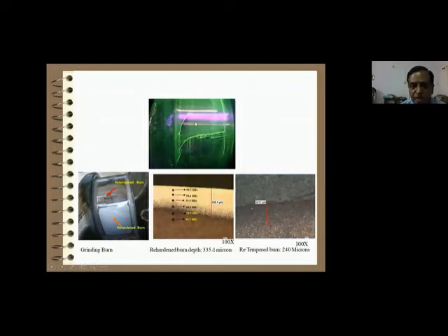Now this is a typical microstructure. After machining a crankshaft, certain defects are seen over here. So to understand what the defect is, a grinding burn test is conducted. You can see the surface, it is a retempered defect over here, retempered burn, here rehardened burn. The gray shade is seen different over here. In this rehardened burn depth, the hardness is very high, 58 HRC, 55 HRC. And this is the retempered burn, around 241 micron depth, where the hardness is less over here.